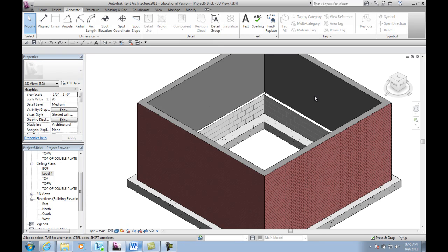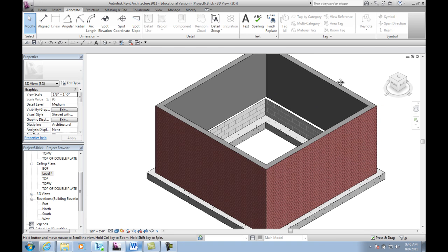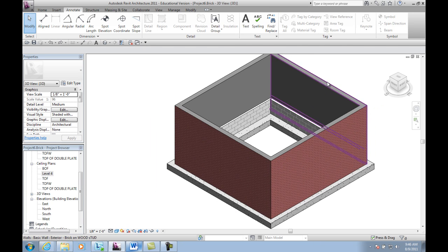Welcome to Project 5, and today we're going to learn how to calculate how many brick and how much mortar we need to make an estimation on putting this brick veneer around this home. Now, a brick veneer is in a residential structure or commercial. What veneer means is just a cover up. It doesn't have any structural load to it.